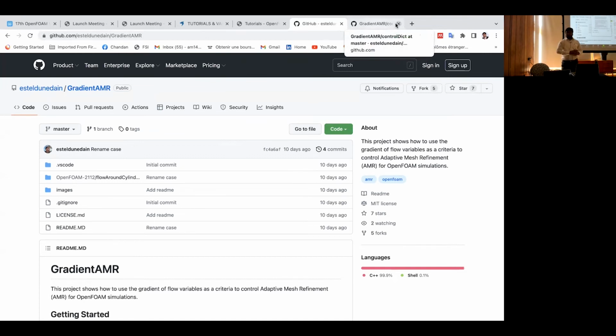How is the inner or outer distance measured? I mean to ask whether it is rectangular or radial, and how far the outer distance should be from the main boundary. Again, this is beyond any thumb rule. It has to be decided on a problem-to-problem basis, and since it's a radial distance, it should obviously be a circular area of cells. It cannot be rectangular.